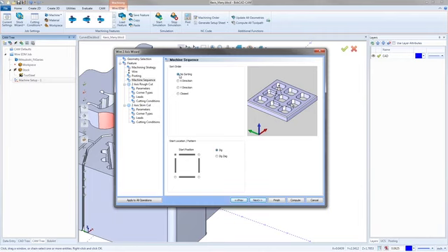And that's the same kind of rule for milling as well. You'll see it on milling and a bunch of the toolpaths, a lot of the 2-axis, that a lot of people always think it's random. It's not random. It's the order it got selected in, but it's random if you drag a box for the geometry. So just below that, we have our start location. This is just saying, if I've got my origin down in this corner here, I may want to start with the pocket closest to that. So I could say start at that lower left-hand corner or wherever you want.